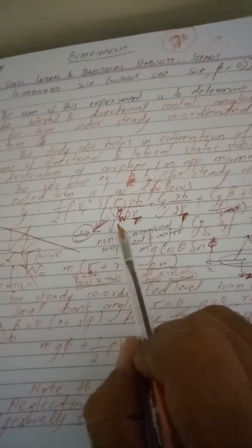Right now, Fy is equal to half rho V of turn squared S times [Cy of wing, pb over 2V of turn, plus Cy r, rb over 2V of turn, that is r by rudder, and Cy beta times beta, plus Cy delta a times delta a, plus Cy delta r times delta r, that is because of the rudder]. And this is the whole equation.